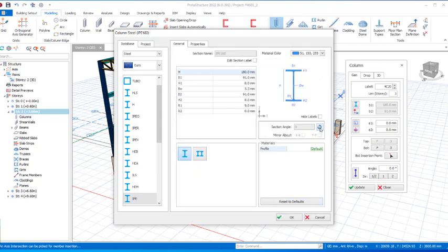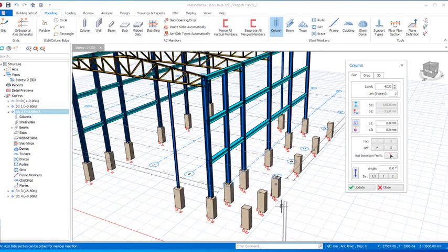We are going to rotate it this way. Click on the OK options. So we will be having the columns right here, but by then we are going to do a little settings over here. We are not going to have 3 again, rather we are going to have only 1, because this is connecting only story 2 and story 1. All right, so we have 1 right there.